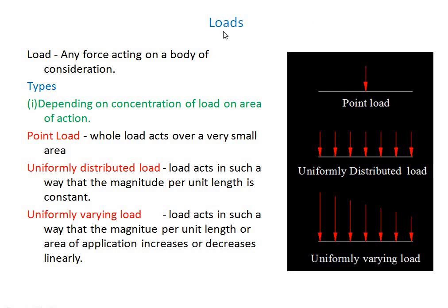Now, loads. The definition of load is any force acting on a body of consideration. We are considering a body and we are going to study that body, and if any force is acting on that body, we call it a load. The types of loading, depending on concentration of load on area of action, are classified as three: point load, uniformly distributed load, and uniformly varying load.